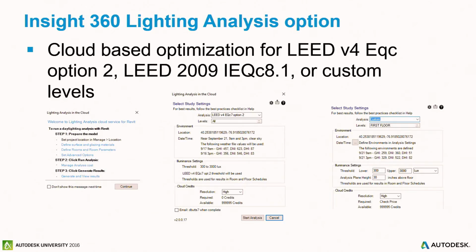Well, it might be in the book somewhere, but I talk about the analytical property of a room and a space. And when you go into a room or a space, there is already an analytical level defined. Have you ever got a room where you got a wall that's sloped like this, right? What happens if my analytical space is at like 2'6", but the wall's really bent out like this? I get a gap right here in my energy model.